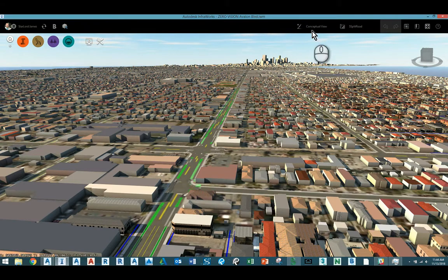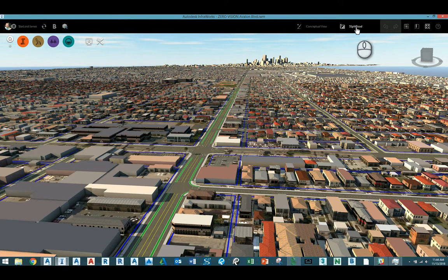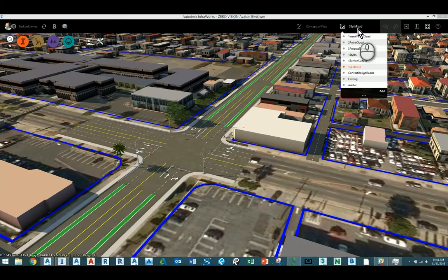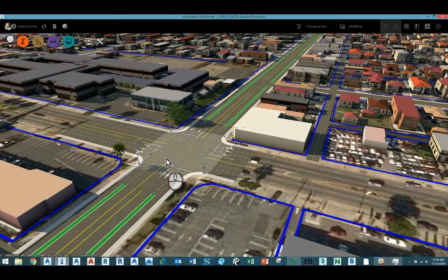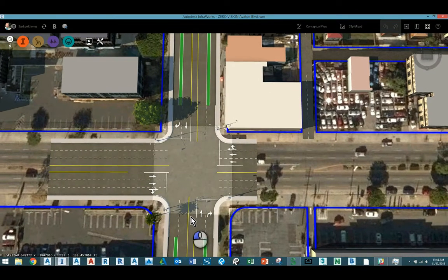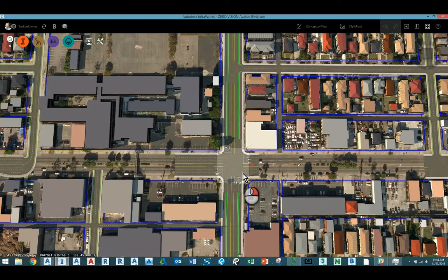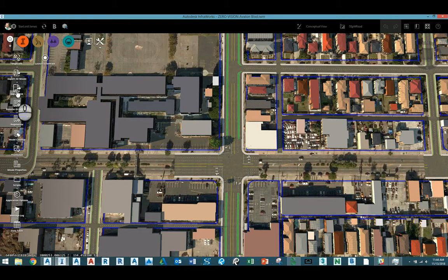Whichever proposal, and I'm talking about the proposals that you make up here, that you want to export to Civil 3D, that's where you would go and make sure that that is the correct proposal that's active. Now, if you have the latest Civil 3D, you can just close this and then open up Civil 3D. This version is 2019 InfraWorks, and I'm using 2019 Civil 3D. However, if you're using an older version of Civil 3D, which definitely happens, there is this Export IMX.